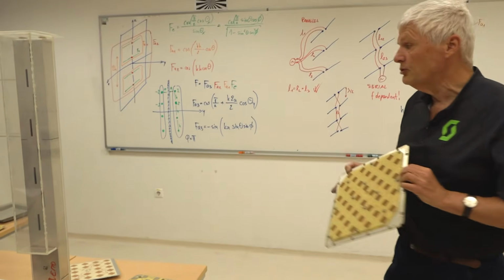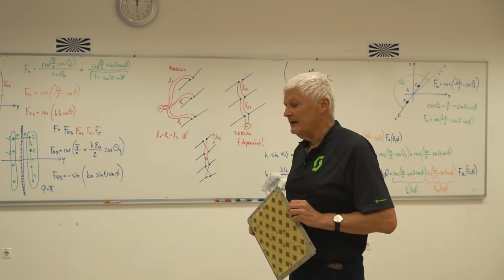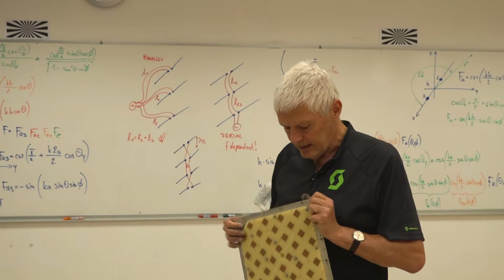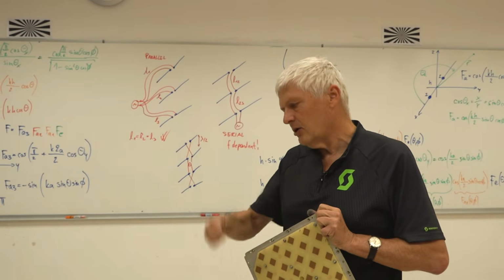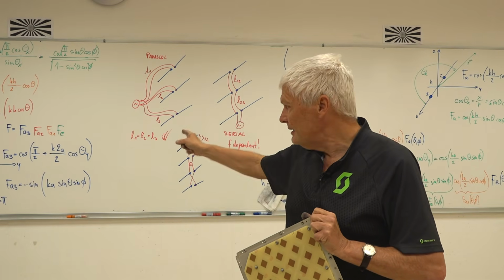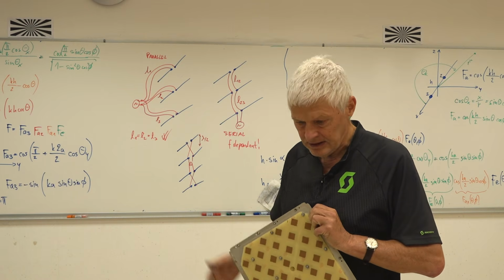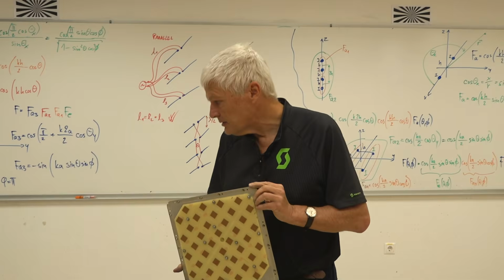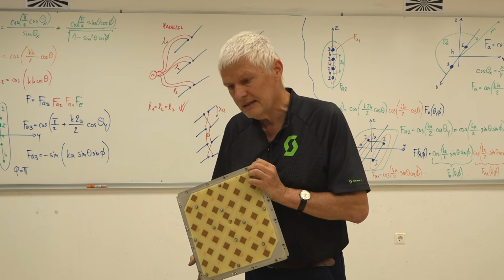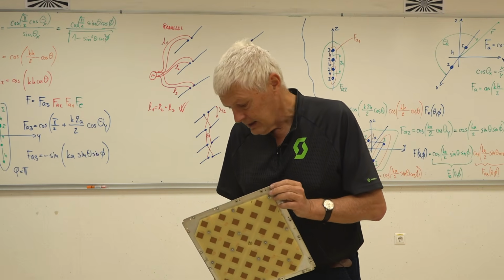The final solution, the most modern, is how to make a steerable array. A steerable array should have each element of the antenna connected to its own electronics, generating the signal with an adjustable phase. So by adjusting the phase, you can adjust the beam of this antenna. And that's the way antennas of Starlink are made, both the user terminal and the Starlink satellites of the satellite internet.